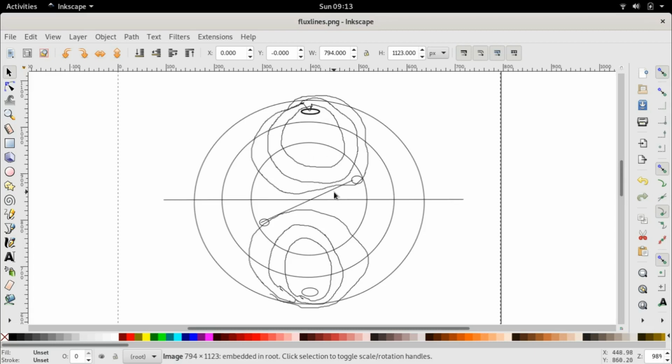So the rotor, even though it's a squirrel cage induction motor and consists of rotor bars along the circumference, we assume for simplicity that it consists of just these two bars or two coils with the same number of turns, producing a similar flux effect, right? So if we consider a single cylindrical rotor, we see that even if the rotor rotates, and we rotate it in different directions, we find that there is absolutely no change in the reluctance of the flux path. For example, if you choose any of these flux lines, there is no change in the reluctance of the path of this flux if the rotor rotates.